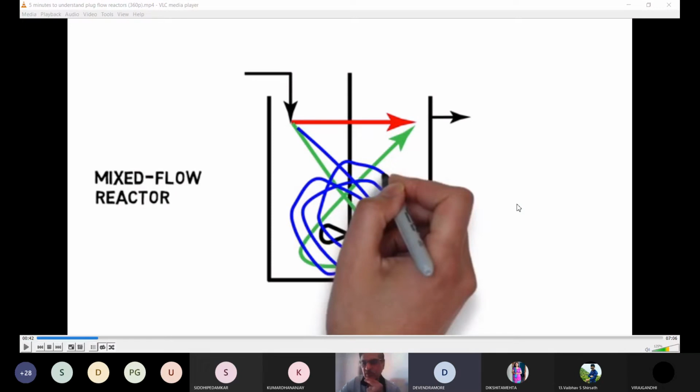Level, we always want to maintain a constant volume in the reactor, right? हमने जो देखा था definition of reaction rate, right? 1 upon V dNA by dt, right? So when we take V inside the derivative, it has to be constant. तो इसीलिए we always कहीं भी जाओ reaction volume constant ही maintain होता है, whether it is PFR or CSTR, because reactor is fixed.